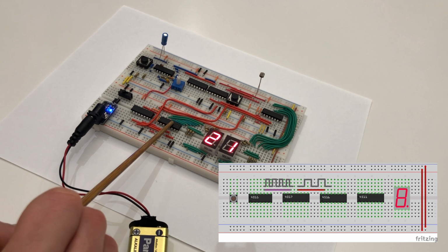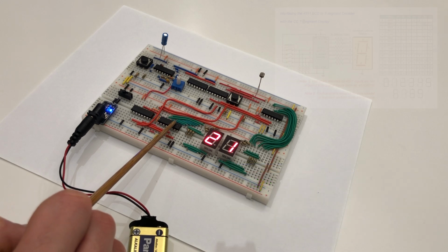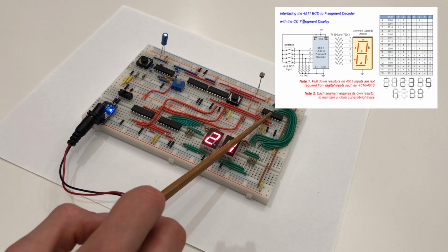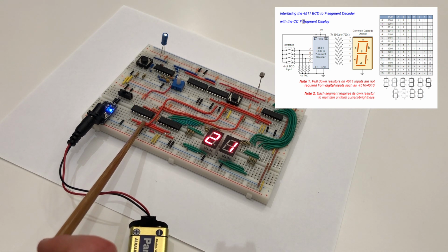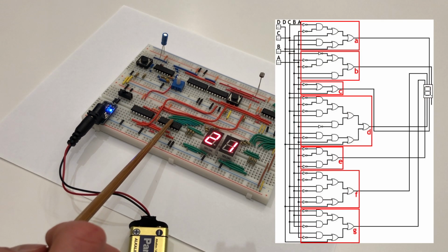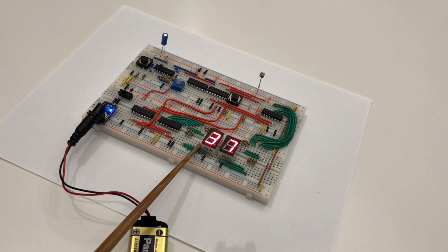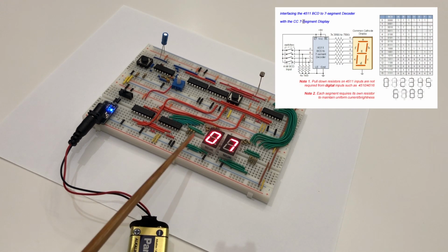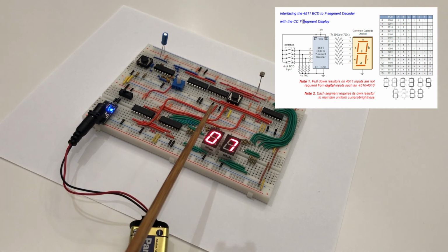The 4511 CMOS IC takes the 4 binary coded decimal (BCD) outputs from the 4510, decodes them, and presents the count on its 7 output pins in 7-segment display format. For example, when it receives 0011, it knows which output pins it should send high to display a 3 when connected to a 7-segment display. This is because of an arrangement of many logic ICs inside behind each of the output pins. The 7-segment cathode display takes the outputs of the 4511 into specific pins to display the count of the clock signal periods in decimal. The reason I have resistors connecting to the 7-segment display is because the 4511 and the 7-segment display both have no built-in resistance.